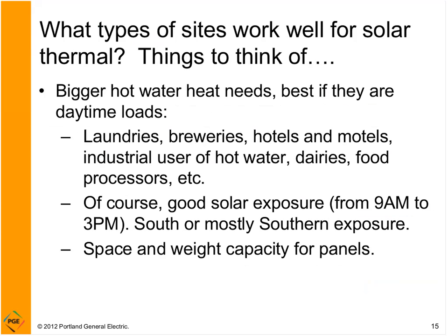So, what type of sites work well for solar thermal? Things to think of as you look at your site are both the load side and the solar exposure side. On the load side, the bigger your hot water needs, the more cost-effective a solar thermal system will be.